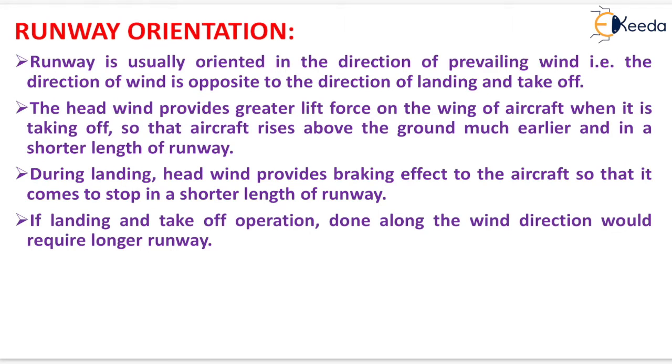During landing, headwind provides braking effect to the aircraft so that it comes to a stop in a shorter length of runway. If landing and takeoff operations are done along the wind direction, they would require a longer runway.